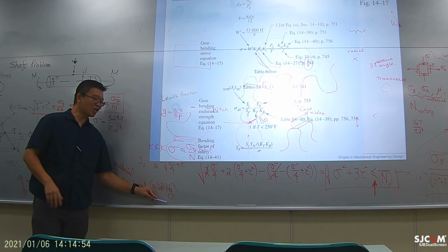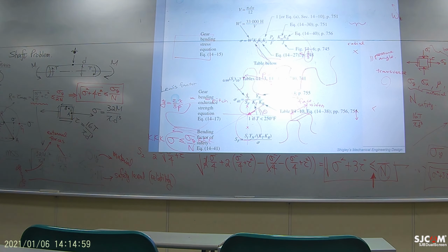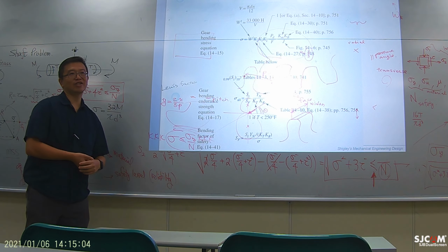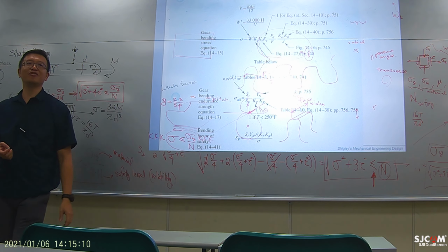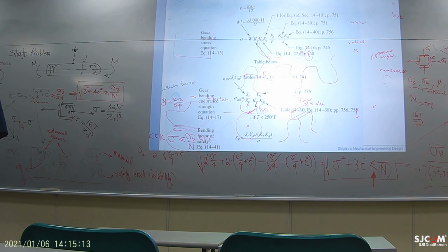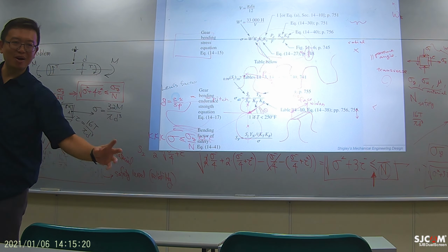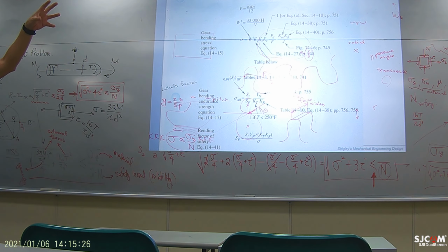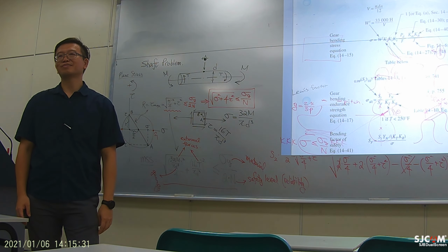Those are correction coefficients. So if you get the concept of why the gear design equation looks like this, then you are not afraid of it. You just need to know that for gears, I need to multiply so many coefficients. But concept-wise, it's all about the stress being smaller than the stress limit divided by safety. That's how I relate the static load model with the gear chapter.